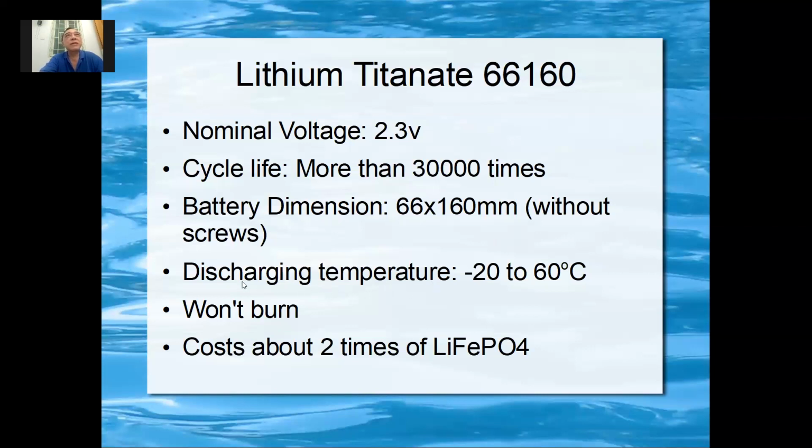Okay, and the other fantastic thing is that the discharging temperature, that means you can use the battery even below freezing point. So especially in countries where there's a winter snow. Okay, so if you use lithium ion and when it is below freezing, your battery cannot work. You try to use it, you can damage the battery. So for lithium titanium, if it's freezing point, you still can use it. Of course, not too low, until -20 only.